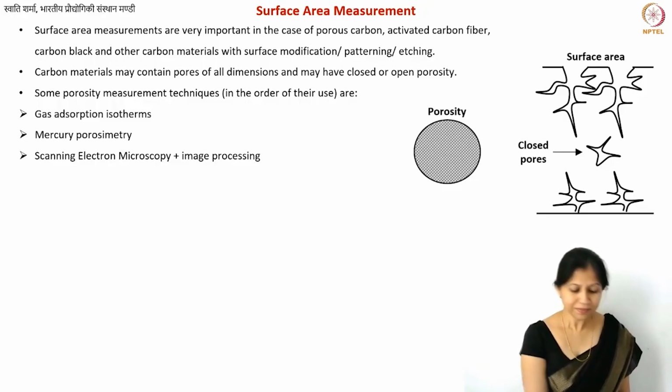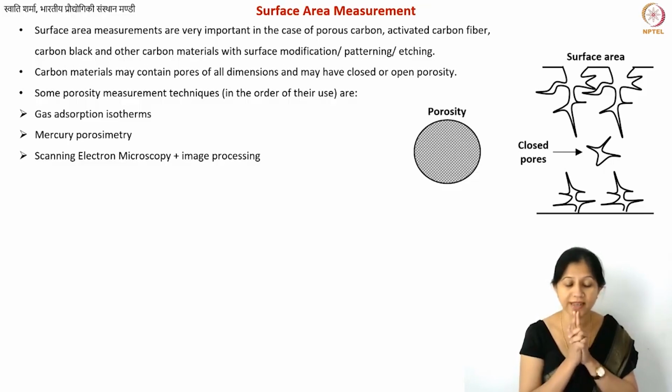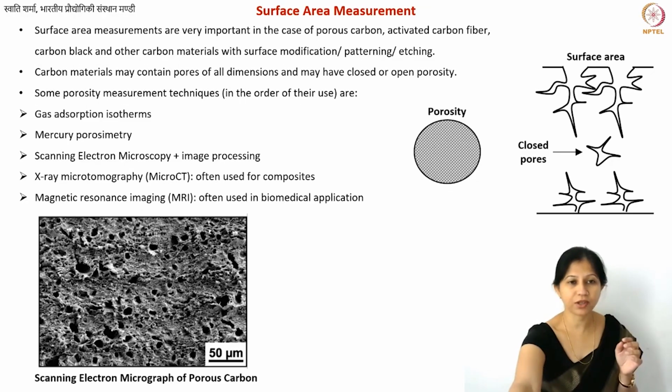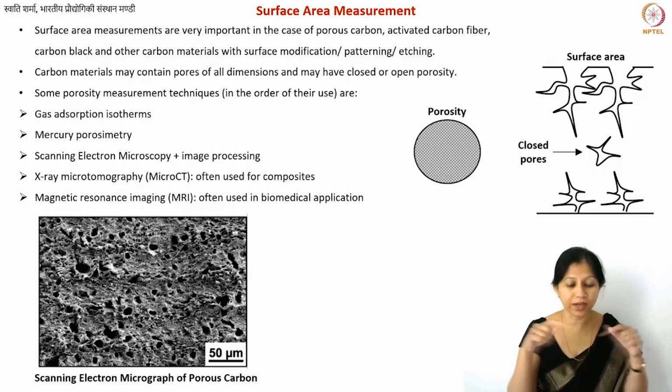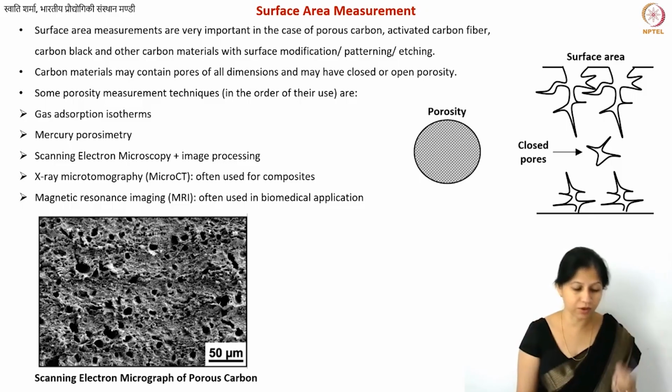This is yet another technique. SEM imaging. So we talked about TEM. SEM, how can we use that? So SEM image, basically, let's see if I have a picture. Yes, I have it here. So SEM image of porous carbon, you can see, will only tell you about the surface, right? Now number one, you should know that you will only know about the surface and not about if your pores are cylindrical or how deep down they go, and also whether or not your pores in the middle of the material, let's say, are connected to the top layer. So you'll only get the top view if you take this kind of standard SEM image, and then you will see that there are some pores.